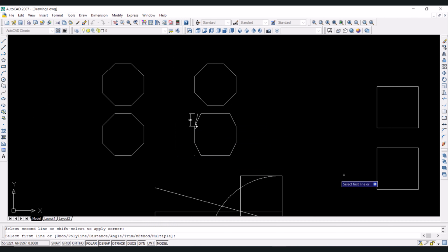But if we use chamfer command now on a polyline, let us see what happens. So let us execute p enter, because polyline was the option starting from capital P. And if you click on this rectangle, now this rectangle looks distorted. Why? Because it follows a specific order. So first horizontal line, then vertical line, then vertical line, horizontal line, then horizontal line, vertical line, then vertical line, horizontal line. So it follows a clockwise direction, and because of that there is no symmetry now.